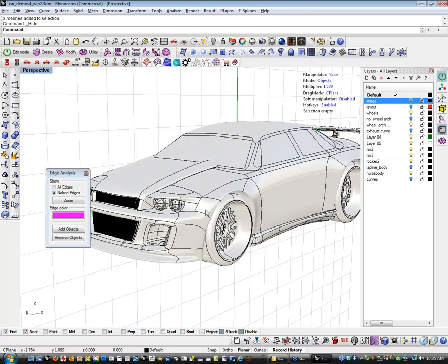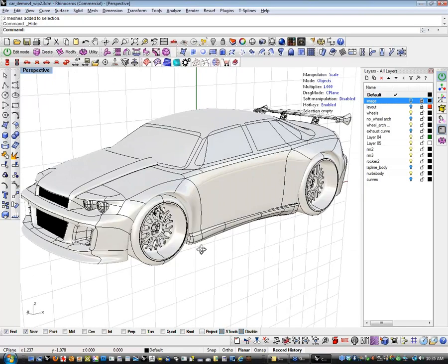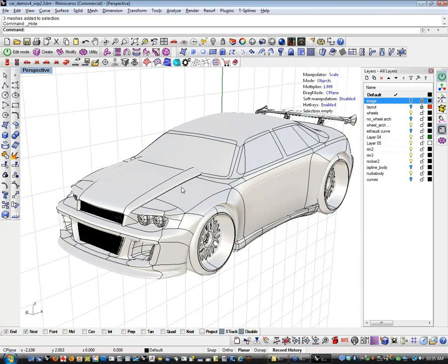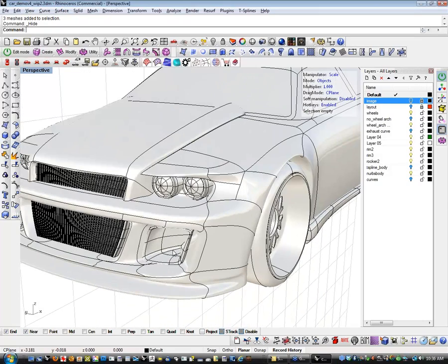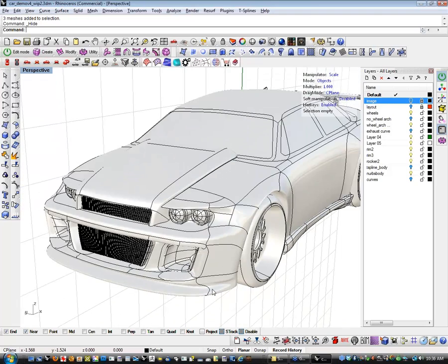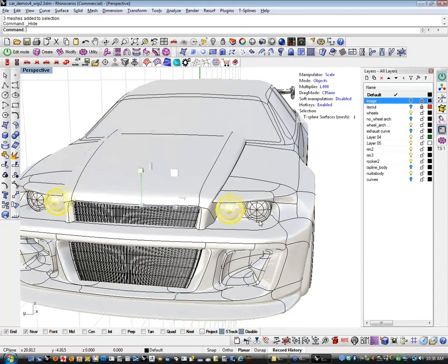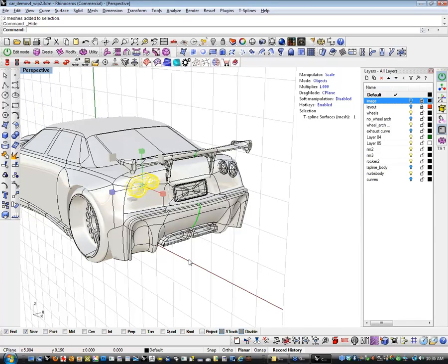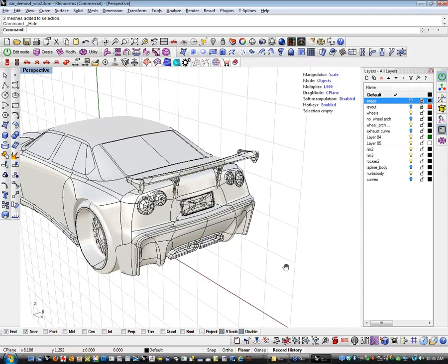And you'll notice that the way that I did this particular model is these are T-Splines parts, the hood, and the body and everything I converted to NURBS, and then I just Booleaned them together. My additional intakes and stuff like that were T-Splines parts. These were imported geometry. Actually, no, those are T-Splines parts I made. And same thing with the taillights, same thing with the exhaust pipes, all that kind of stuff. Same thing with the license plate.